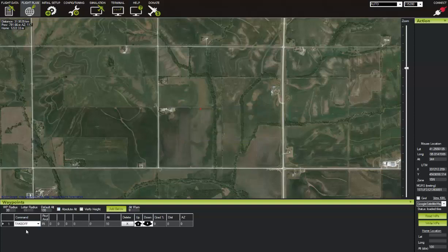You can see here in the Waypoints menu that we have a takeoff command programmed in at 10 meters in altitude, and when the UAV hits 3 meters per second in velocity and 10 meters in altitude, the automatic mode will take over and the UAV will fly through all of the predefined waypoints that have been programmed into its memory, which we will set up right now. So once you've synced the UAV with the ground station control software, all of the waypoints will be programmed in the UAV's memory automatically, and will stay programmed in even without a direct link to the UAV.